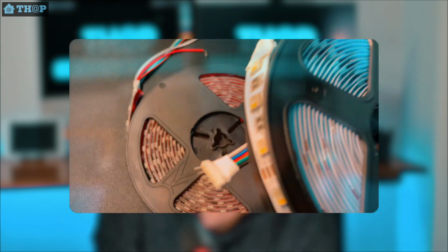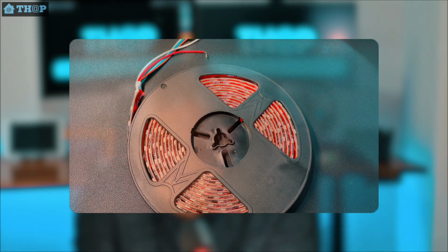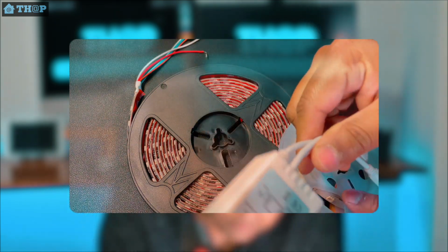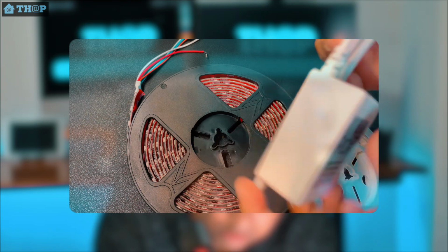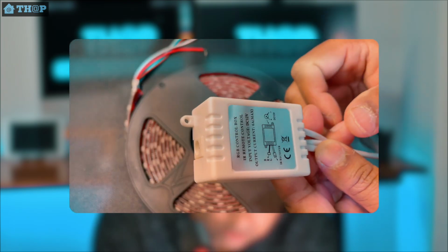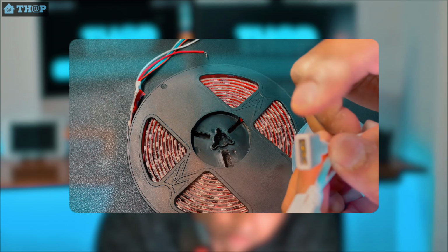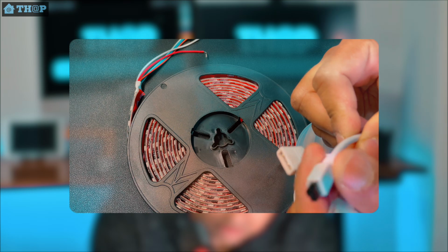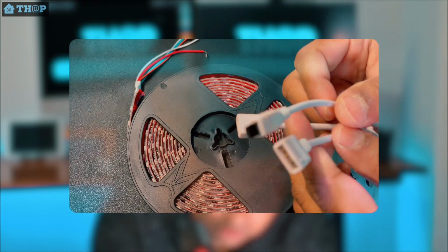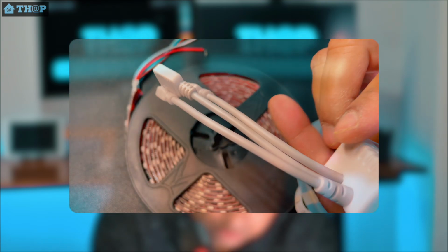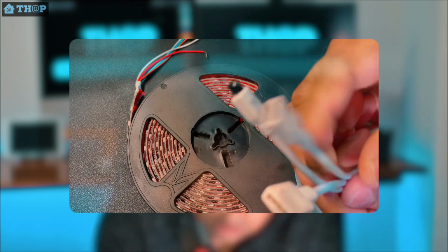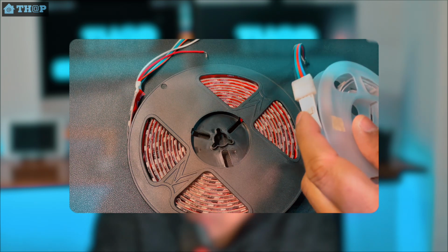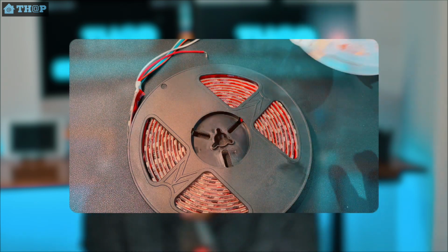of white. And the way to control these LEDs is generally these come with these controllers for the analog LEDs. These are either 12 volt or 24. These operate generally from 12 to 24 volts, and the input is this 4-pin or 5-pin LED, and they also come with this kind of basic remote, and you can do one or multiple LEDs with this one controller, and you can plug in the power input which is through this. And you can use some kind of smart plug to control this if you want some more automation.